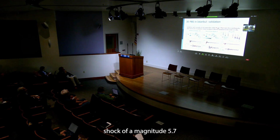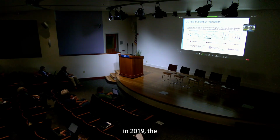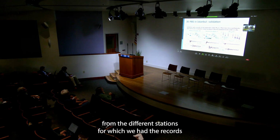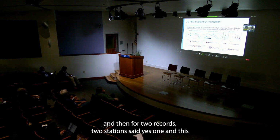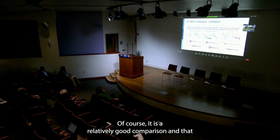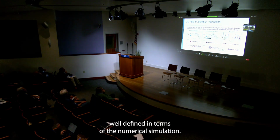First of all, the validation phase was based on the records obtained in the Istanbul area from a relatively small shock of a magnitude 5.7 earthquake along the branch of the Marmara Sea fault in 2019. The comparison was rather good. Of course, the dots that you see denote the goodness of fit from the different stations for which we had the records, and then for two stations, the S1 and the S10, you can also see the comparison of the time histories that were simulated. Of course, it is a relatively good comparison that at least gives the idea that the geological model was relatively well defined in terms of the numerical simulation.